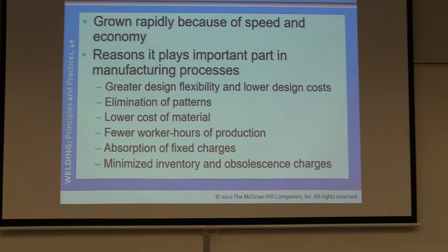People say, well, steel's so expensive versus something plastic. It is. However, it depends on what it is used for, okay? Rolled steel is a stronger, stiffer, more uniform material than castings. Therefore, fewer pounds are required to do an equivalent job. Also, since rolled steel costs 1/4 to 1/2 as much as casting, the cost of material is cut by as much as 3/4 by using welded steel fabrication. By replacing riveting, welding fabrication saves more than 35%. Wow, that's crazy.